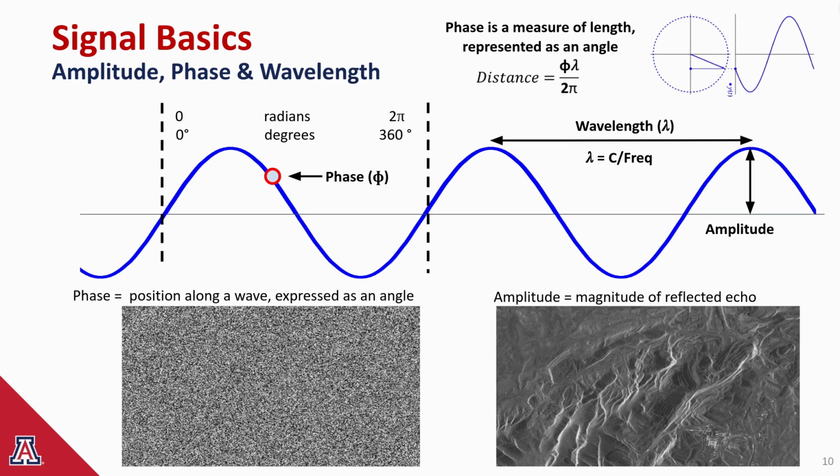When the pulse gets back to the satellite, there is some non-integer fractional wave left over, and it's the length of this fractional wave that is recorded as my phase value for some given pixel, nothing else. We have no knowledge of the many millions of waves that occurred along the pulse's journey, just the final fractional segment. So it stands to reason that for any pixel, the phase value will be between 0 and 360 degrees.